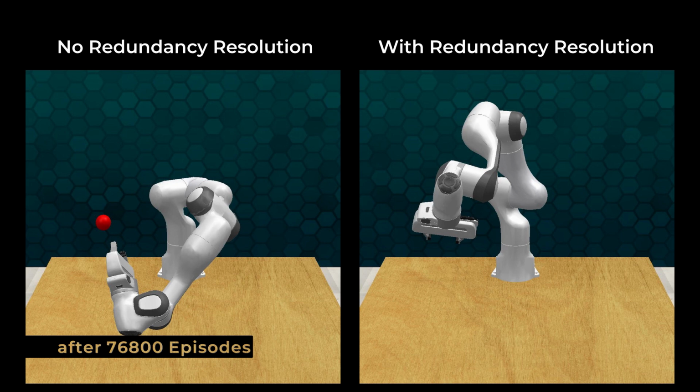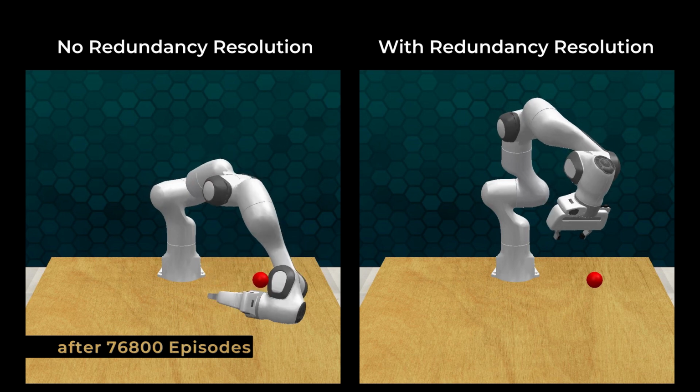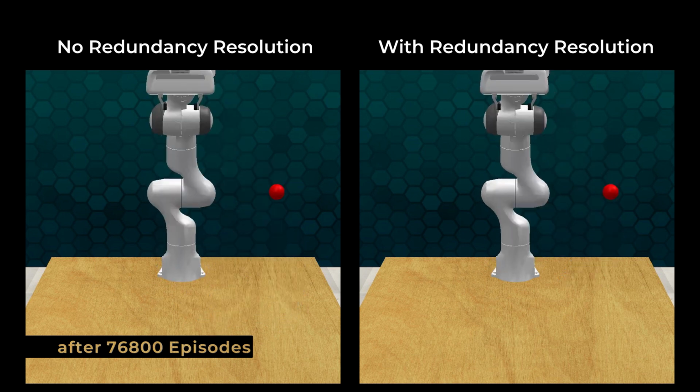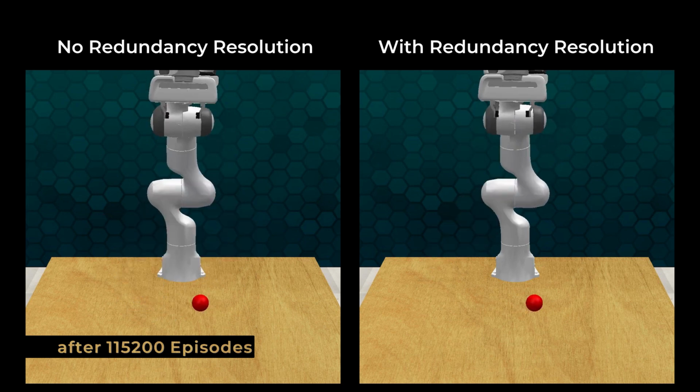It is expected that this is because at the beginning of training, the agent focuses on approaching the spawn boundary of the target. After learning how to approach the spawn boundary, the agent then focuses on the single target, which causes this backflipping behavior. The evolution strategy with redundancy resolution did not learn a backflipping behavior and has an overall more upright position of the gripper.